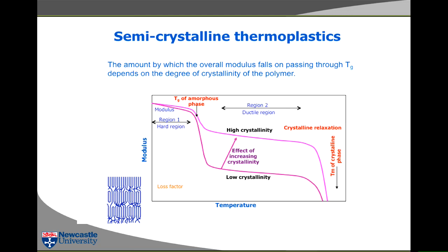Just remember 210 gigapascals. That's one thing that you'll always remember because you do all the calculations. Right? So steel has the Young's modulus of 210 gigapascals. The materials I'm talking about have a Young's modulus of about 2 gigapascals. So they're a lot less stiff than steel. So at low temperature, you've got a modulus like that.